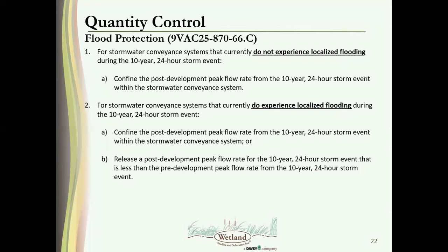If it does, and if you can prove it does, let me say that again, if you can prove it does, it floods at that 10-year, or at that limits of analysis, then what you have to show is for that 10-year storm, your project site is not increasing any of the flows. So my site is basically contributing a negligible amount for the 10-year, 24-hour design storm, okay?